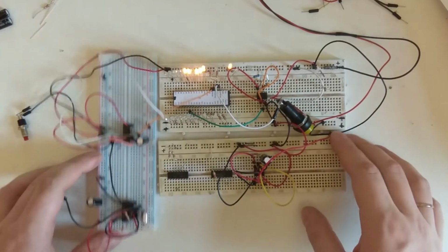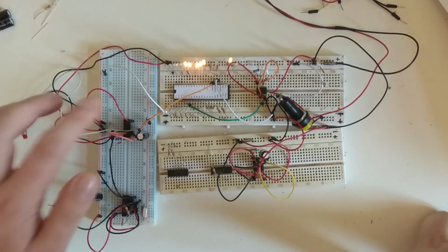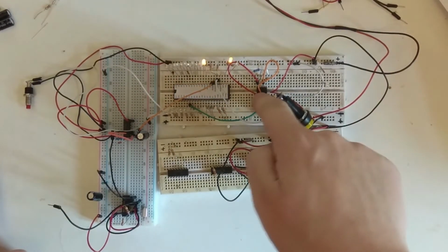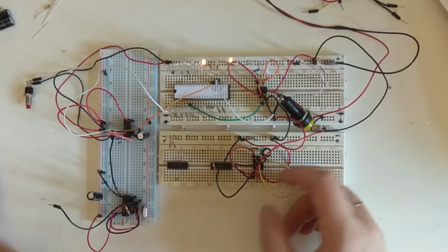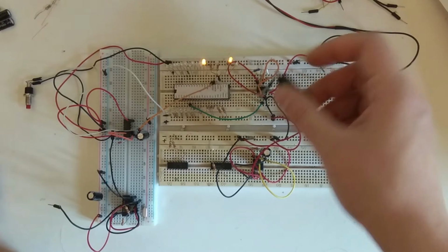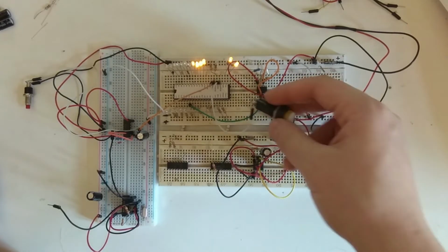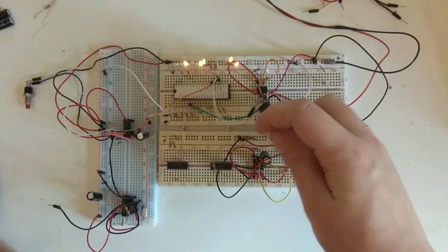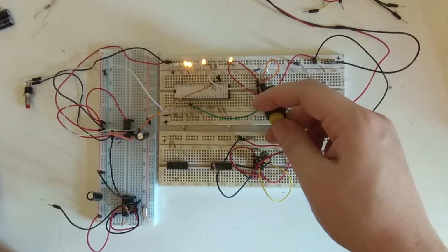So I've got the little prototype system here, breadboarded up with the fast clock over here. This is not even connected at the moment. The reset circuitry over here resets just fine, and the fast running clock over here, and the one-shot over here, implemented in 2 555s. At the moment, I just have a pull-up resistor on here and a switch to ground, and this actually works. Oh, there's my multimeter. This works surprisingly well. I'll just stop it. It doesn't have any debouncing circuitry, but it seems to work just about fine.